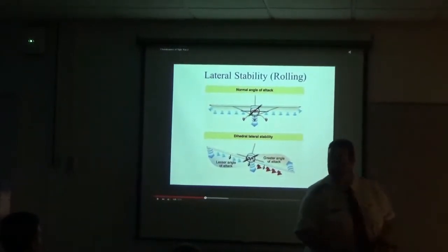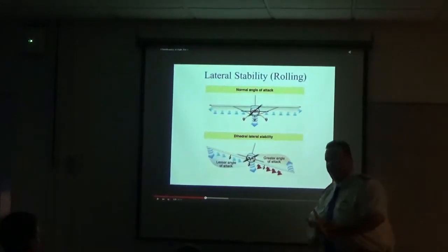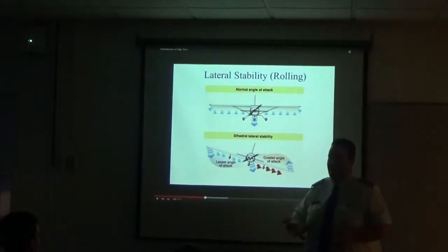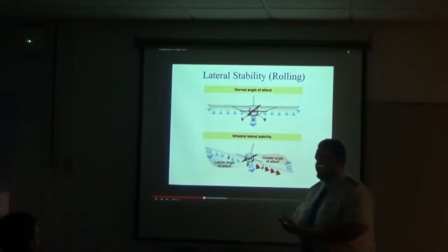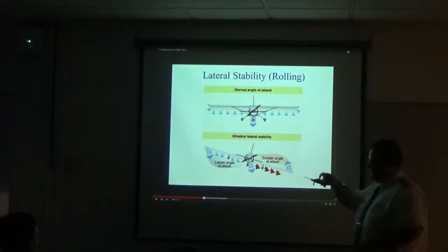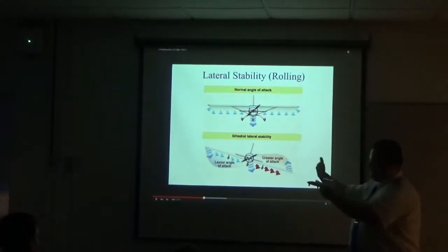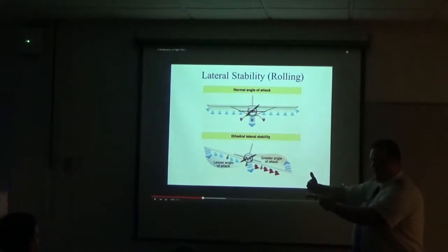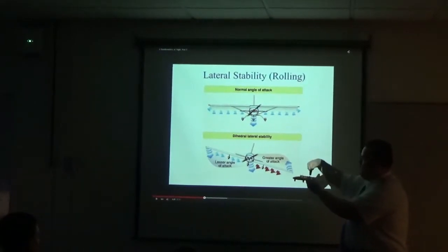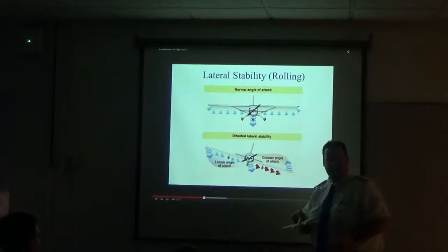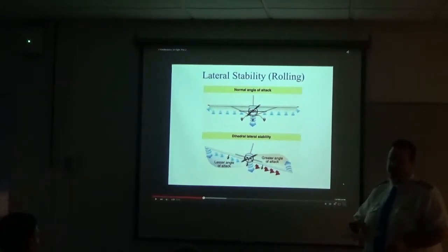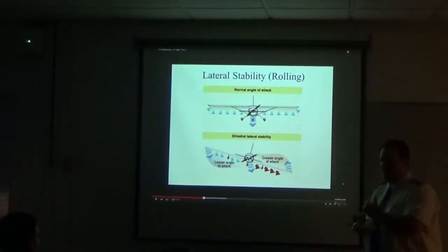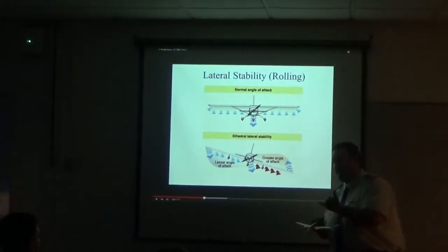So you load it up with fuel, your friends, some food, some drinks, and you go to take off. But you didn't do proper weight and balance. You put some of your heavier friends in the back seat, and of course all your supplies in the back as well. That's going to make the center of gravity farther back behind the aircraft, which can be extremely dangerous if you stall the aircraft.